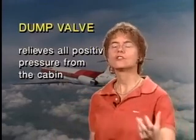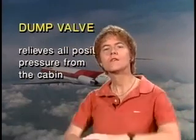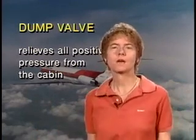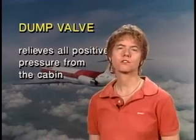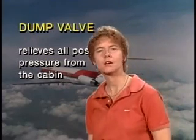And one way to get rid of excess pressure, if it looks like you're about to get it, is to open the dump valve. The purpose of the dump valve in a pressurization system is to relieve all positive pressure from the cabin. So when you open the dump valve, basically you've taken the cabin to normal atmospheric pressure, whatever that may be, and you've gotten rid of the pressure differential, and you have relieved the positive pressure from the cabin, and that gets rid of the stress on the aircraft.